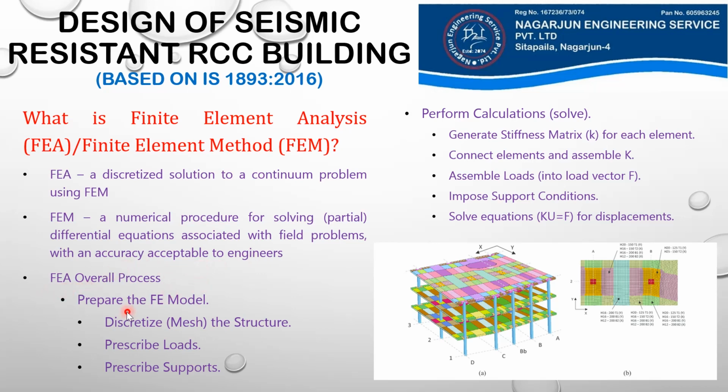The overall process is we first have to prepare the finite element model. As I have talked, our workflow will be first modeling, then analysis, and then design. While preparing the finite element model, we have to discretize the structure. We have to break it down into its components. We have to prescribe the loads. The loads are given by different codes, and we will be prescribing those loads upon those elements.